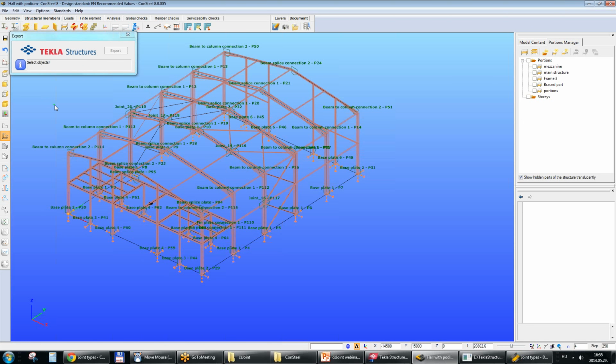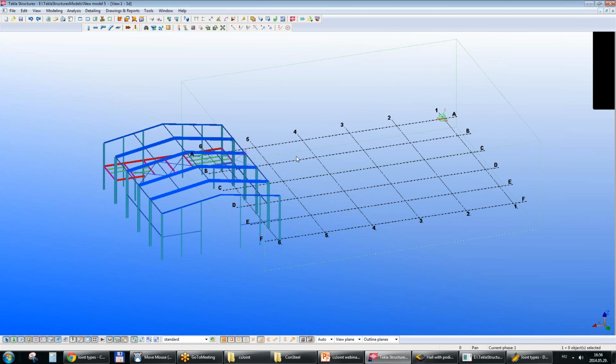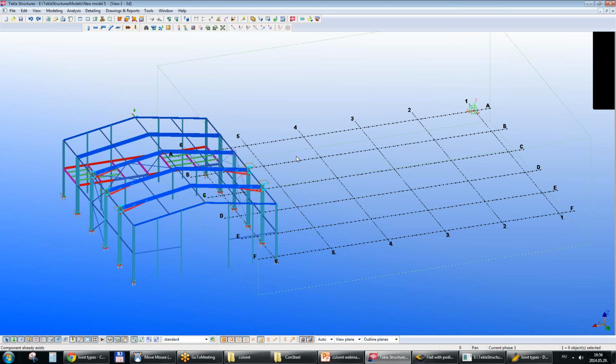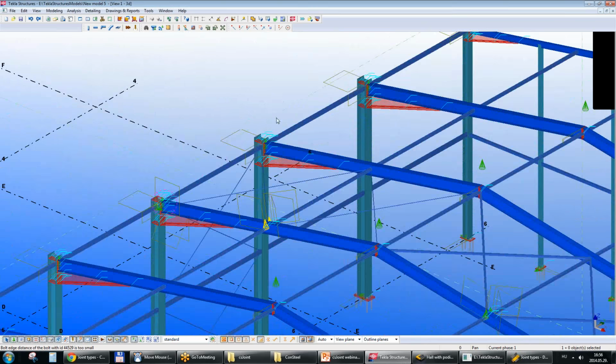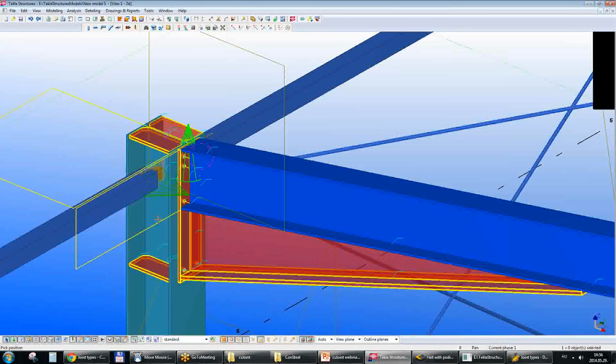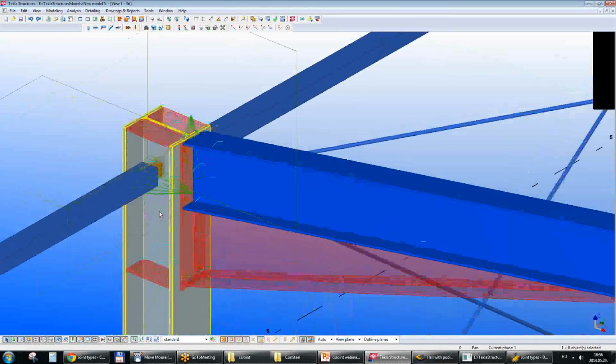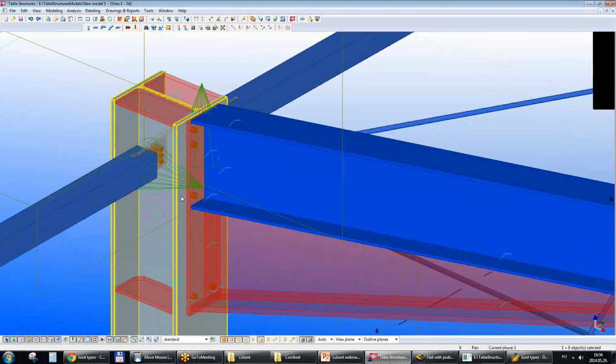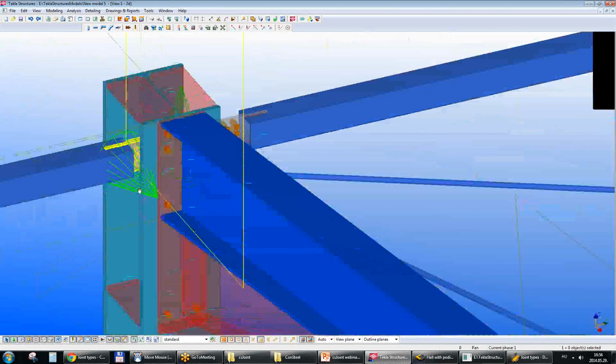Okay, and then pick the reference point in Tekla structures. So then I go to Tekla, pick a point, and then we can see that the whole model with the elements is first exported, and then all the joints, all the connections are exported. I now look for the connection. This is the connection that we identified and created now with this end plate connection, with the compression post connection and the tension bar connection.